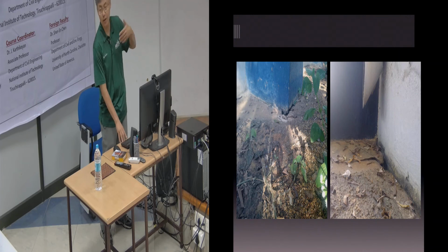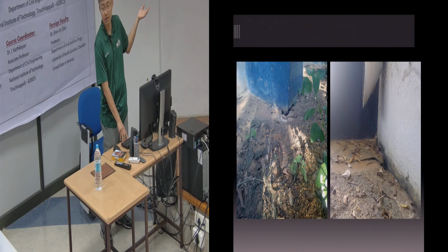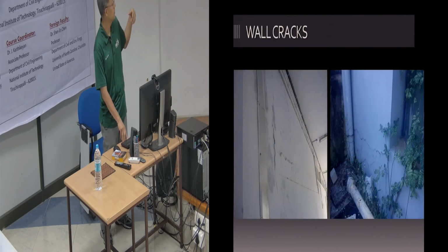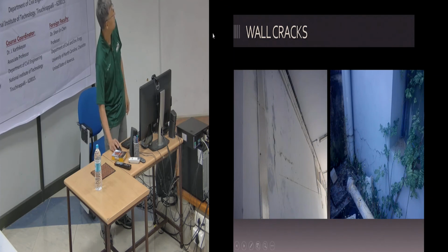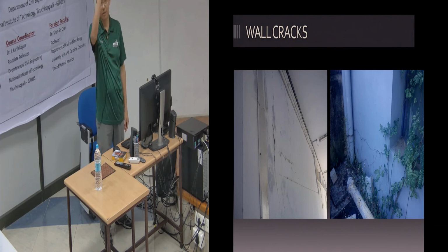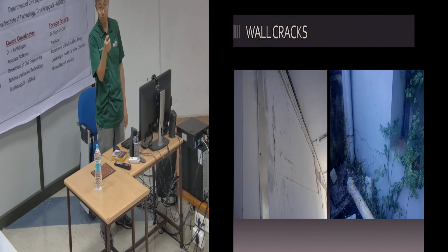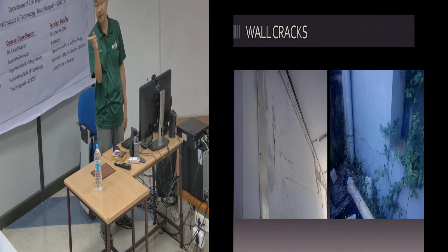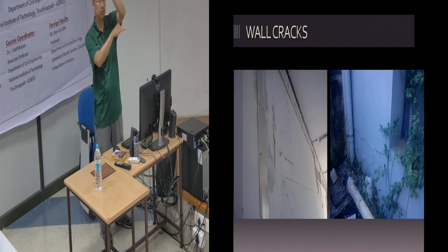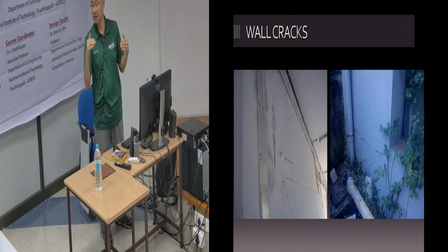But you know, we are civil engineers. We know these are not indicating any issue of instability. It's just because of the drainage of the soil. But the wall cracks and so forth will be more critical. Those are always the painting that exposes the cracking. Because most of the walls are bricks, the crack pattern will be very interesting for you to analyze. Some of those column-beam shear movements and punching shear are something that maybe you can observe.